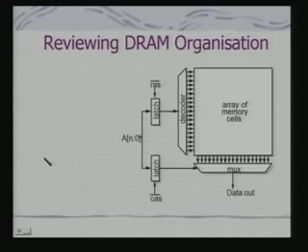Then let us look at this DRAM access. So, what do you mean by internal operation? The question is, what do I mean by internal operation? Internal operation means it is when the processor is executing instructions, say ARM, it requires registers which are involved in the operation. So, it does not require a memory access. That operation can continue without the memory access.